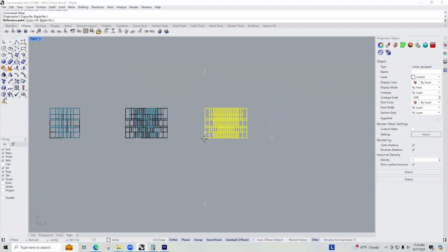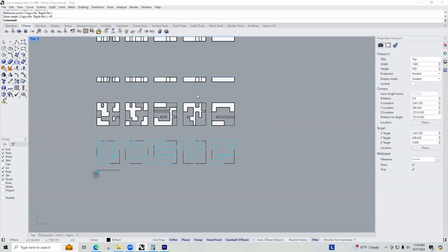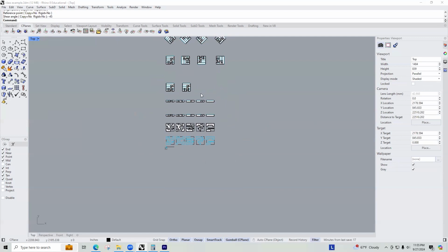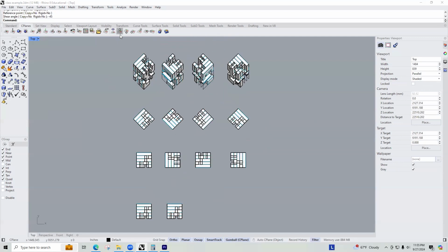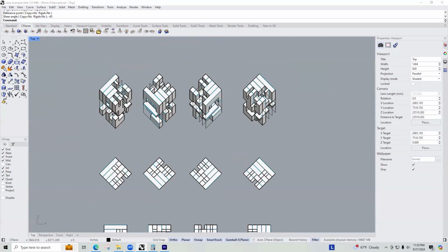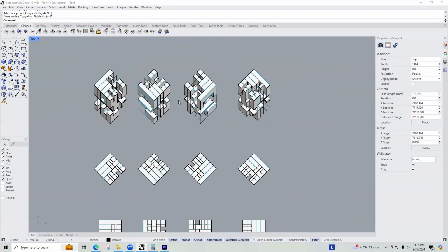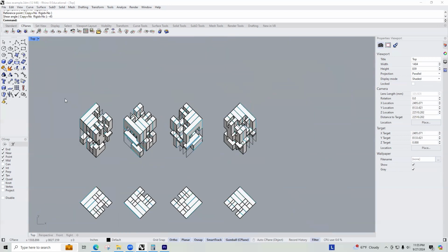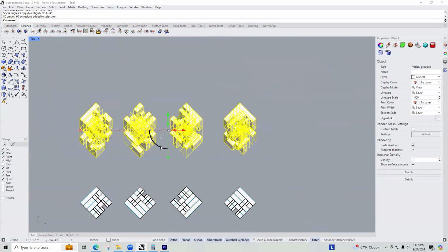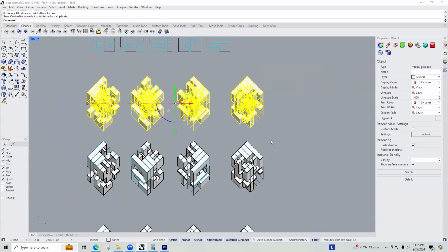So I'm going to pick my start point, which is just a base point, pick a vertical point for my reference point, and then I'm going to type in -45. Remember, we rotated our models 45, now we're shearing it 45. All right, so after we shear it, when we're in plan view, it looks like we're looking at it in 3D. And so this is very dynamic, it's measurable, and you can save this view, but you can also duplicate it again.